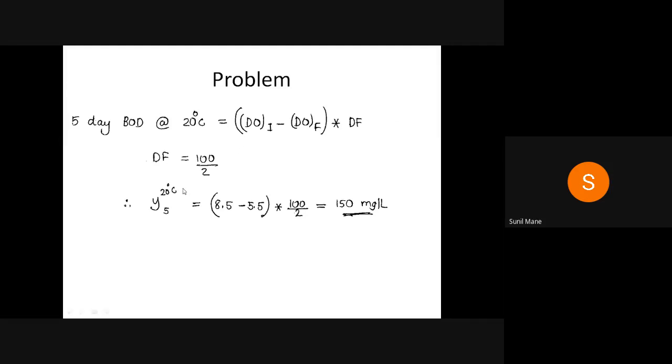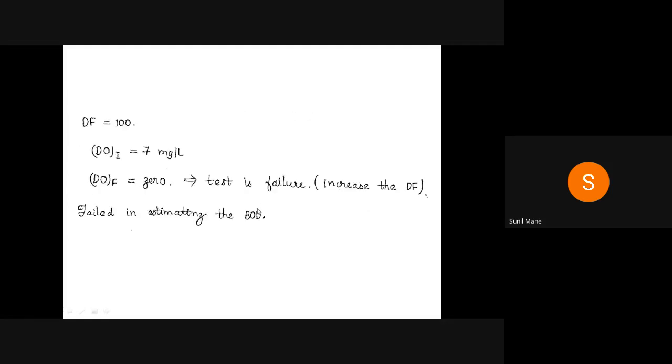Even if we are utilizing a single sewage and going for multiple dilution factors, the result is not going to change. But we have to carry out those things so that the results are not failed results. Initial oxygen reading it is going to give, and afterwards after 5 days, the result should not be zero. Okay, so one problem I'll take, the problem is like this.